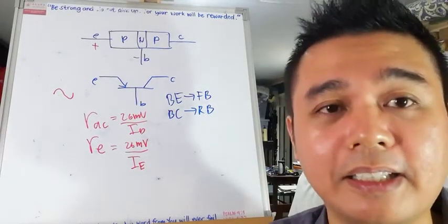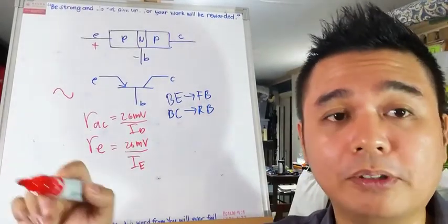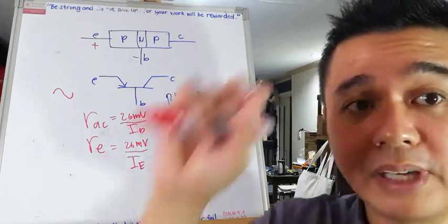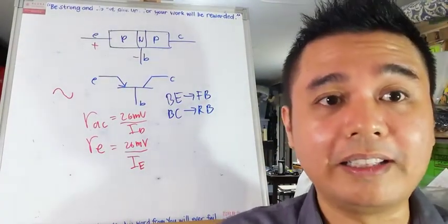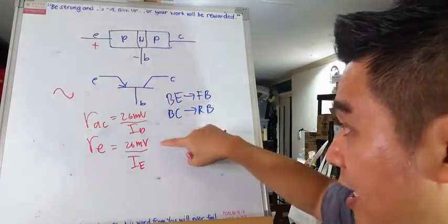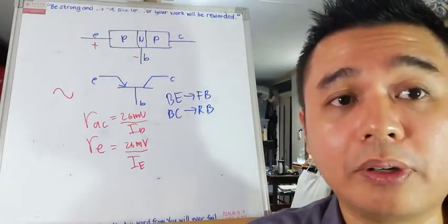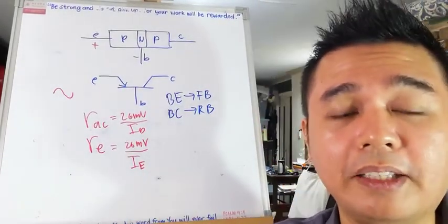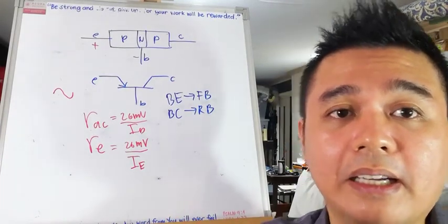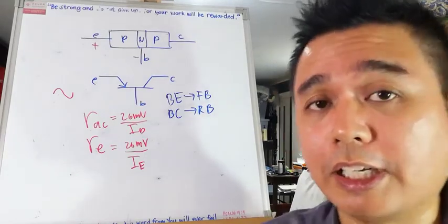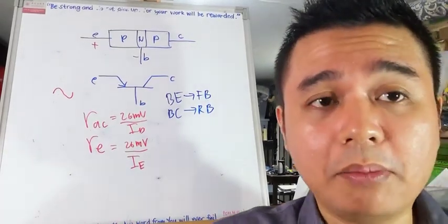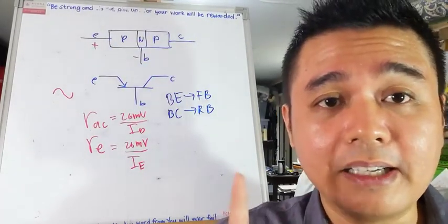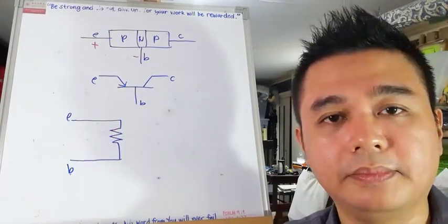Because remember, in our characteristic curve, we have the middle of our sine wave. So our AC signal will swing around the level of that emitter current. Alright? So this will be the equation we will use to represent the input side of our R sub E model. Our objective is that the input side is represented by the R sub E model. So, it depends on the configuration. In the common base, since we have a PN junction, it can be represented as a single resistor, R sub E.